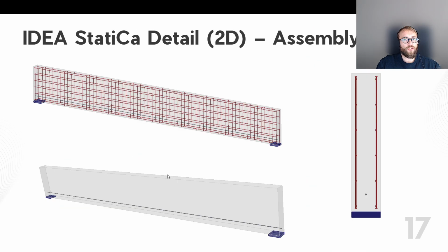And we are moving to IDEA StatiCa for the details. I just replicated the reinforcement I applied to the whole model, which is in total 10.3 meters in length, because the 10 meters is from the center of the support to the center of the support, and the width of the supports is 0.3 meters in total, 0.15 on each side.